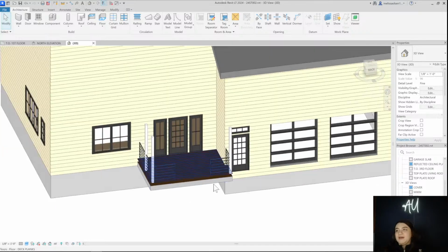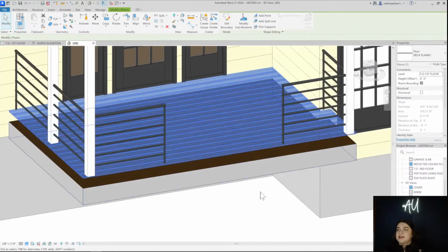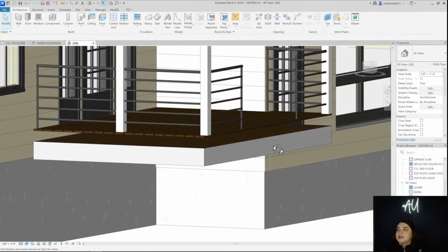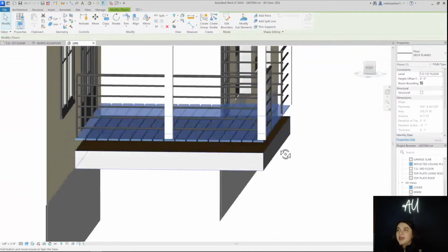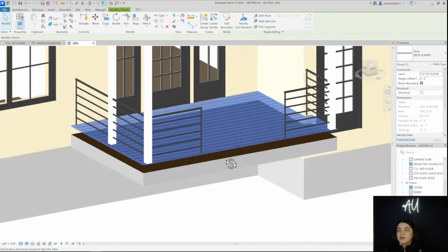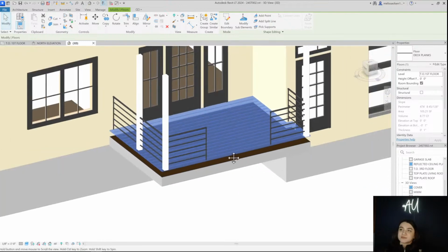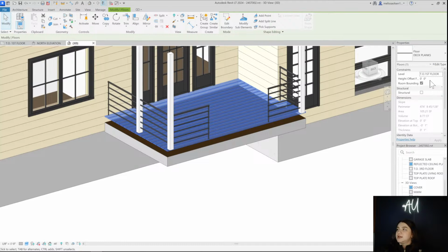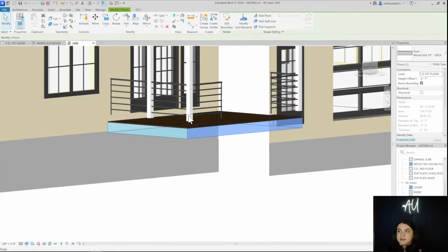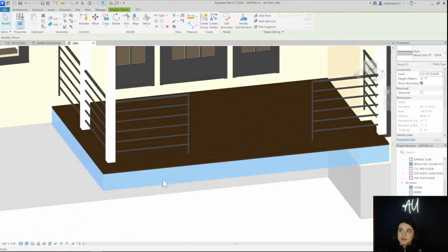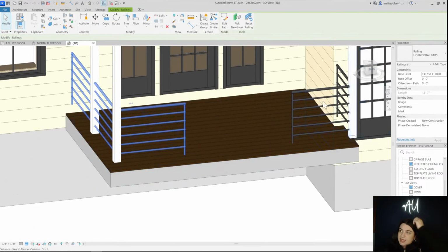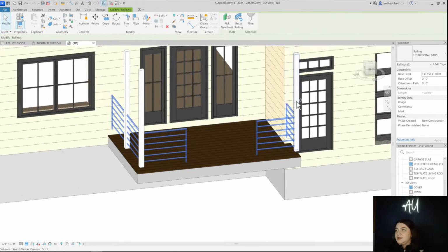And now we have these 3D planks of the decking. And when you bring that into Lumion or a secondary rendering software, it's pretty fantastic. So I'm going to do negative 6 inches to accommodate for the 1 inch height, so it sits in on top. And then we're going to move this down and these down.